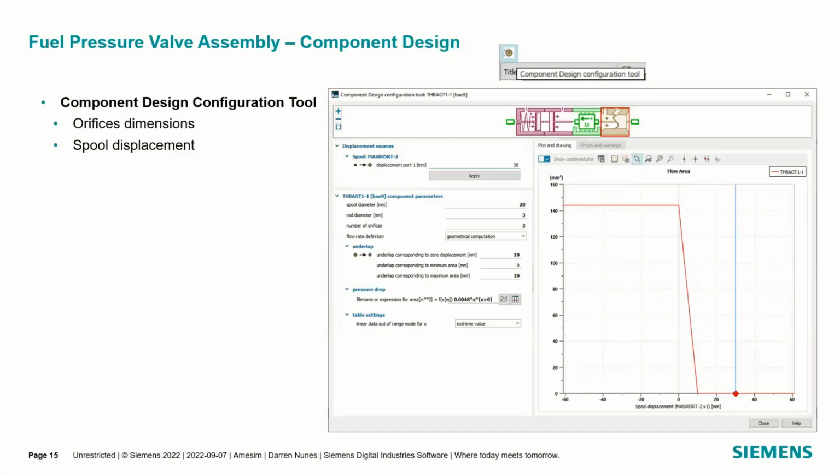We did this analysis based on mechanical end stops. For the pneumatic chamber, we adjust the piston size. It must be large enough to counter the spring force with that high pressure to keep the valve closed. For the variable orifices next to the combustion chamber, we use a check valve to avoid any backflow, which you saw in that previous slide. Because the combustion chamber pressure is normally high, we use the variable orifice to keep the pressure of the MMH, to model that burst disc that normally explodes when there's a certain pressurization.